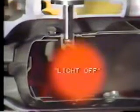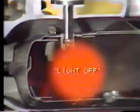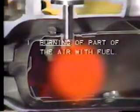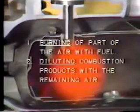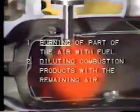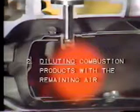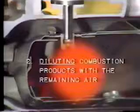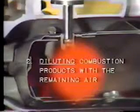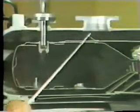Ignition occurs when a spark is applied to this air-fuel mixture and burning begins. This is often called light-off. The total combustion process is divided into two steps. First, the burning of part of the air with fuel, and second, diluting the combustion products with the remaining air. It is in this second step that all the air becomes heated, causing rapid expansion, which is used to drive the turbine.